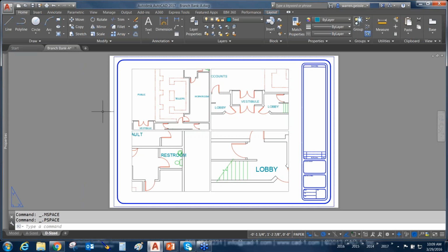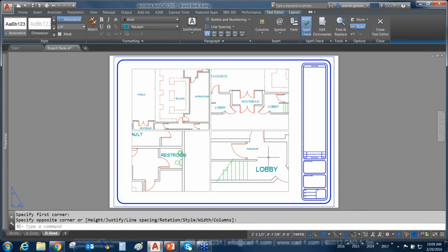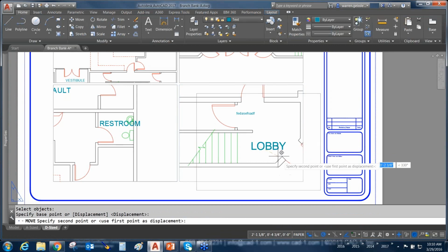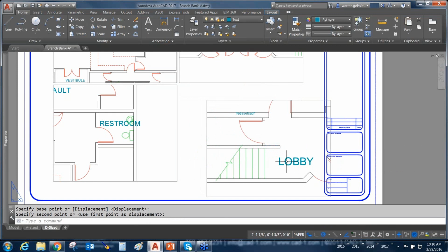However, having said that, if you conform to the architectural graphic standards of drafting, if you're submitting this to an approving agency, if this is a construction document of any kind, then what you see in front of you is a no-no. I've got text of all different sizes in here. Now, all of my annotation is supposed to conform to just one size. How we dealt with this in the past was, well, we had a few different ways, actually. One method was we would put our text on top of the viewport, drawing in a little piece of text there. Now, the problem with that is that if I were to move the viewport or do anything else or erase the viewport, the text doesn't move with it.